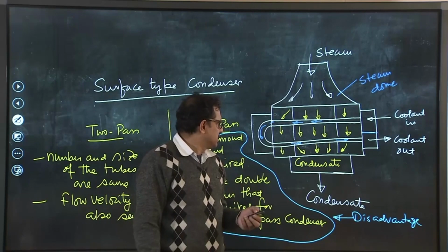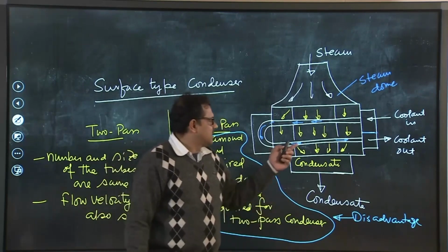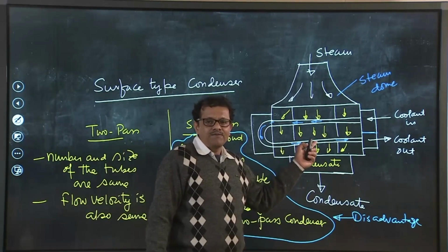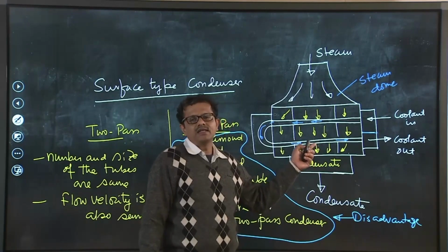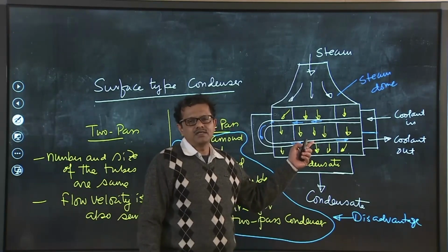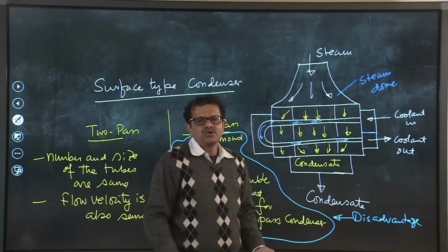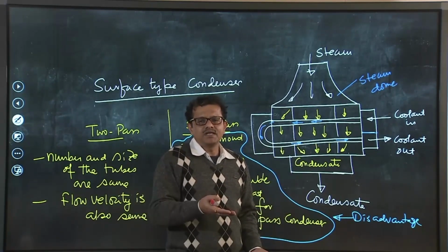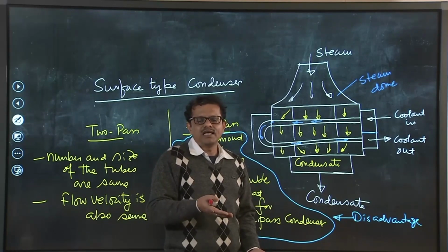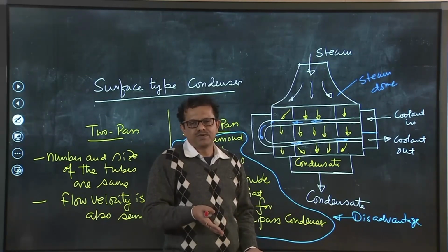But the question is, we can understand that if you would like to have coolant available at the inlet of the pump, will be having temperature maybe 25 or 30. So, the saturation pressure at that temperature already I have mentioned that it is way less than the atmospheric pressure.